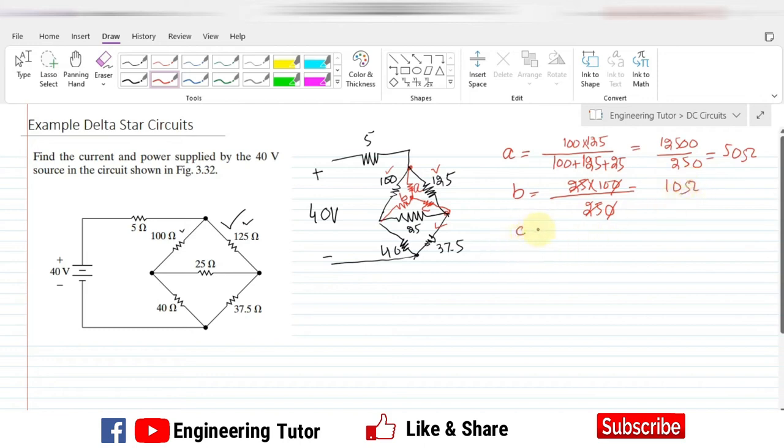Similarly for finding the value of C, the denominator will again be 250 ohm, and the numerator will be 25 multiplied by 125. Simplifying it, this gives me 12.5 ohm. So these are the three resistors for which we have found the values.